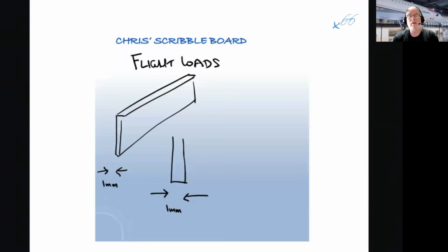We all know that every gram of weight in an aircraft counts. So aircraft skins, although made from aluminium alloy, weigh tons when you add all the skins together. So if designers were ever to try to reduce the weight without compromising the structural integrity of the aircraft, this is where they would do it. Imagine the thinnest skin that could survive a 1G flight. What's a 1G flight? A straight and level flight with no side loads, with no effect on it.